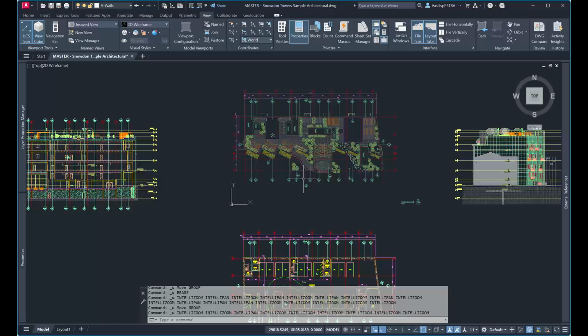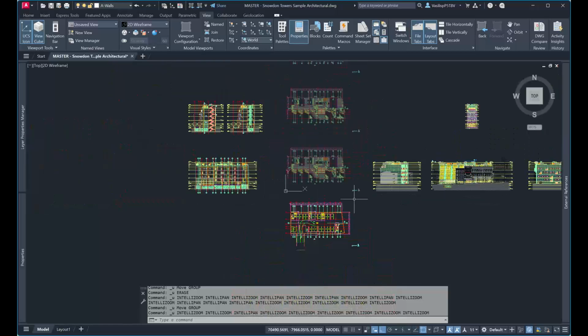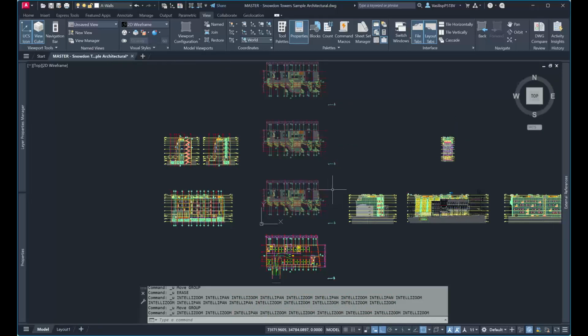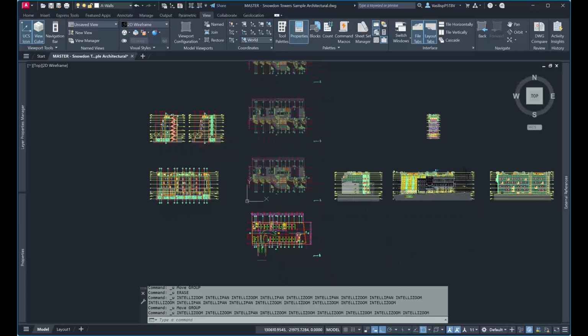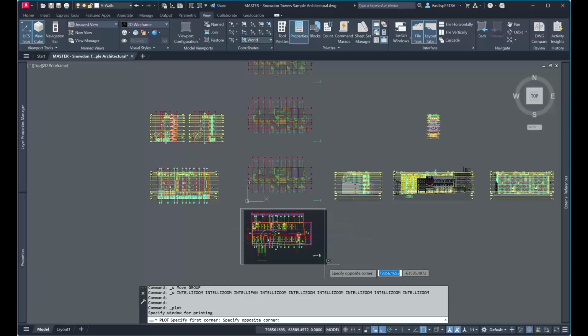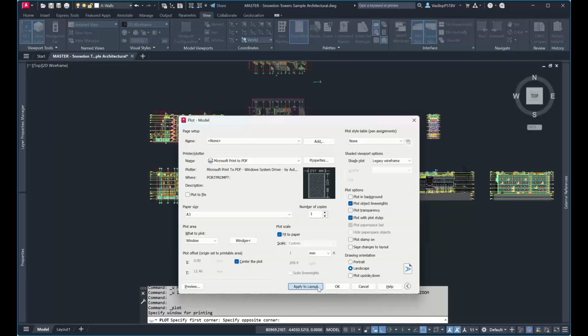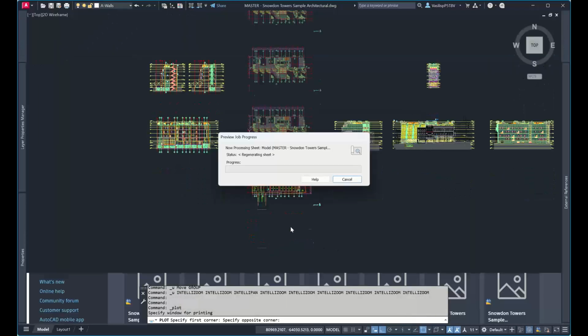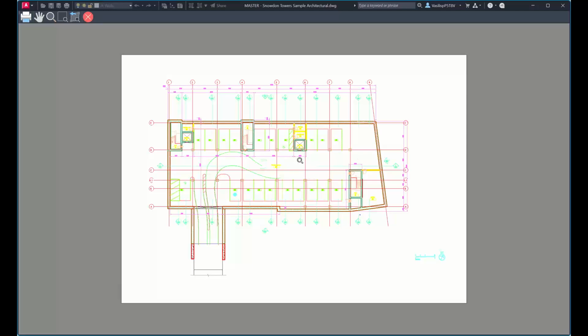The next thing we need to present here is how you create documentation from each program. Here in AutoCAD, pressing Ctrl P, most people will choose a window, create a legend there, apply, see the preview, everything is inside, make some adjustments, most probably for the colors.